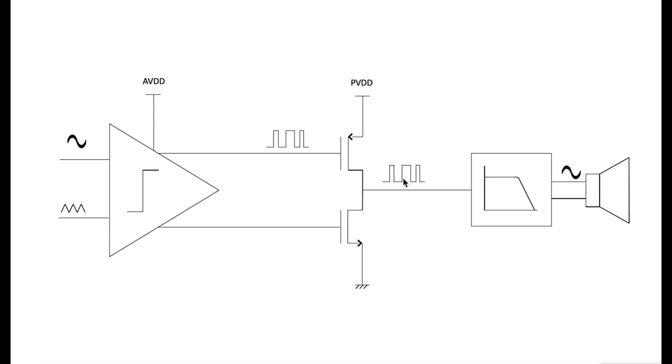The reason for the high efficiency of the Class D design is that the output devices are either in the on or off state, being driven by a square wave, compared to the linear audio amplifier, where the output devices are either in the active or saturation region, where they constantly draw current. The Class D design can theoretically achieve 100% power efficiency.